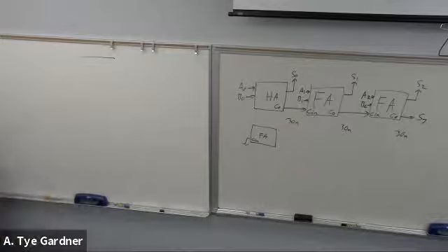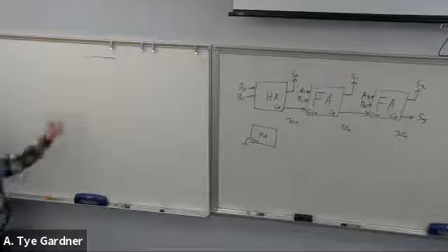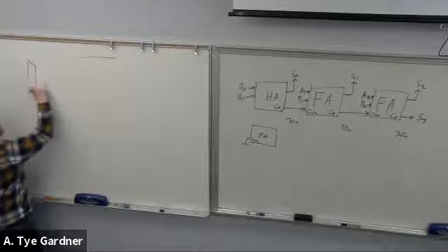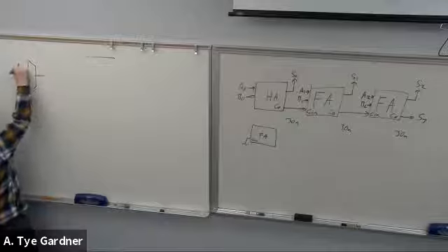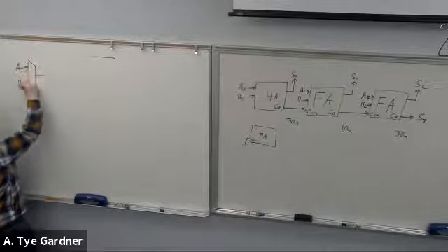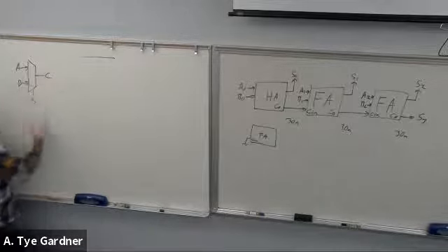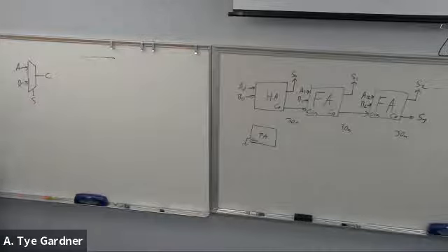Okay, so the next one we've used a lot. The reason we use it a lot is because it's important and it confuses students. It is the MUX, the multiplexer. It takes three inputs really, A, B, and S, or select, where C is equal to A when select is 0, and is equal to B when select is 1. It's just directing the flow of data. It's choosing where the data is coming from.